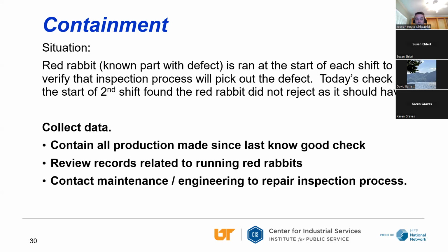We should contain all production since the last known good check. Maybe that was the previous shift. Some companies do red rabbits once a week, and I have had some companies that do their masters once a week or once a month. That's a high risk, because if you find a problem, you've got a week's worth of production to contain.